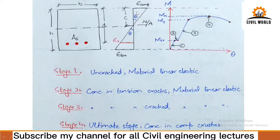So if we plot a graph between the moment at some particular instant and the curvature at that particular instant, once you start loading the beam, there is an increase in the applied moment and an increase in the curvature. It starts to increase linearly till the point cracks are initiated in the bottom fibers of the concrete, because it has very low tensile strength capacity.